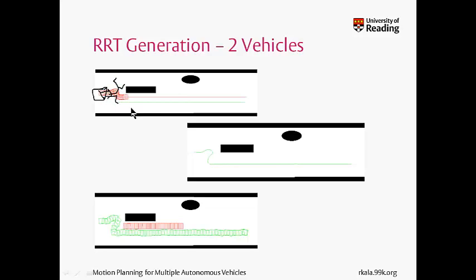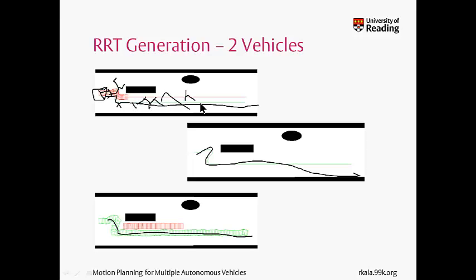It carried out this expansion in any order. It saw a vehicle, it said that it tried to overcome from the left. It simultaneously at some instance tried to overtake from the right. Once this node was generated, it saw that now I can simply travel right towards the goal. This is the smoothened version of the same trajectory, and it simply travels straight to the goal. The basic RRT algorithm, we know that would have continued expansion like this all around in this narrow region until it would have reached the end, so I save a lot of time.